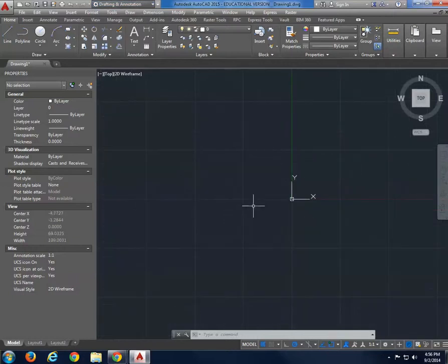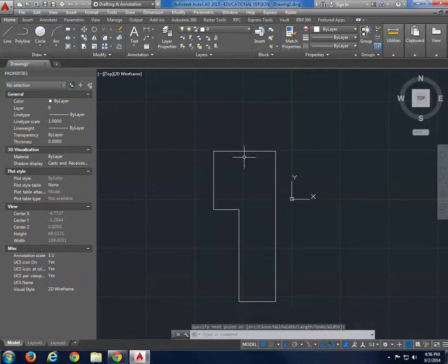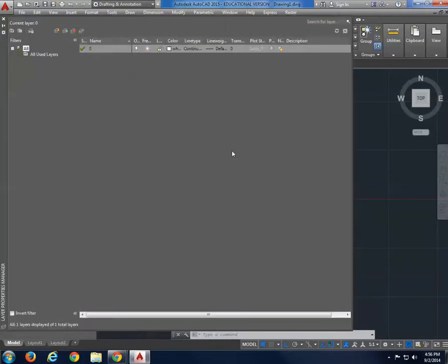Before doing that, I mean, you can do it, but I'm going to do a polyline in my drafting test, F8, and I'm going to do a site. Okay. You know that you can create your layers, LA, and expand your layers, and you know that for each layer it's recommended that you change the color so you can print afterwards the way you want it to print.